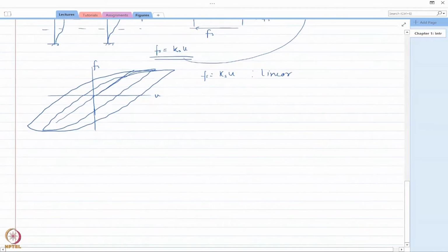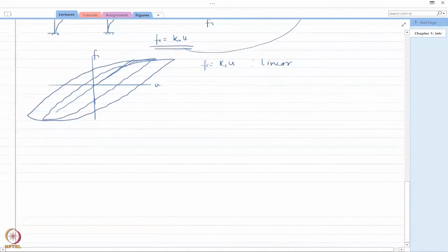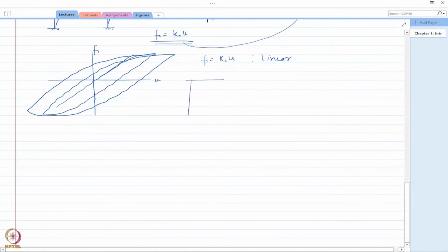All right. Now let us consider two extreme cases for this frame here. By two extreme cases, I mean, in one case, this is very flexible, so that the flexural rigidity EI is 0, and then again you apply the force. And in the second case, it is very rigid, so that EI is equal to infinity. Now if you apply the force and are asked to tell what would be the equivalent stiffness of this system, how would you do that?